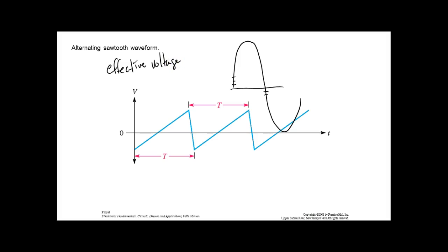Now what the effective voltage is, if I take this AC and I put it across a resistor, it's going to give us work. Because even though the current is changing, it's still current. If you put current through a resistor, you get work, right? When you talk about Watt's law, there's no such thing as a negative wattage, right? All your wattage is wattage. So 100 watts is 100 watts. There's no such thing as a negative 100 watts. Everybody understand that? So negative current flow produces the exact same power as positive if the current flow is the same.